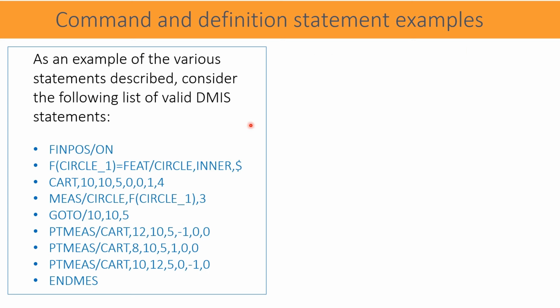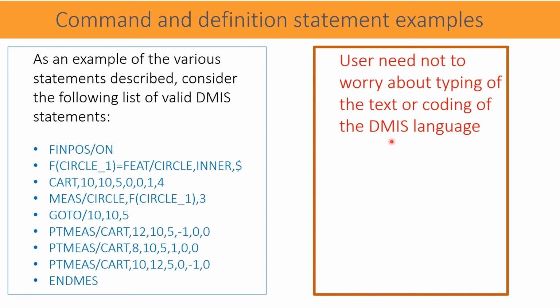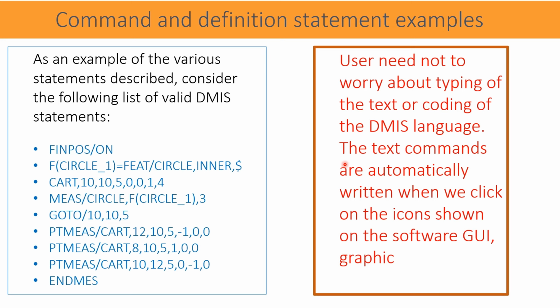Many users may think: how can I write a program in such a typical kind of text, as shown in the program? But the user need not worry about typing the text or coding the DMIS language. The text commands are automatically written. I repeat it because it is very important. The text commands are automatically written when we click on the icons shown on the software GUI, graphic user interface.